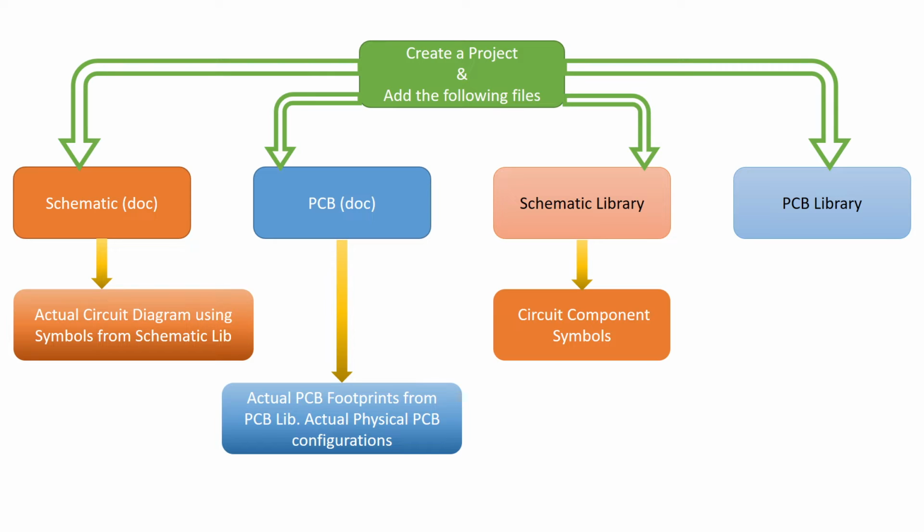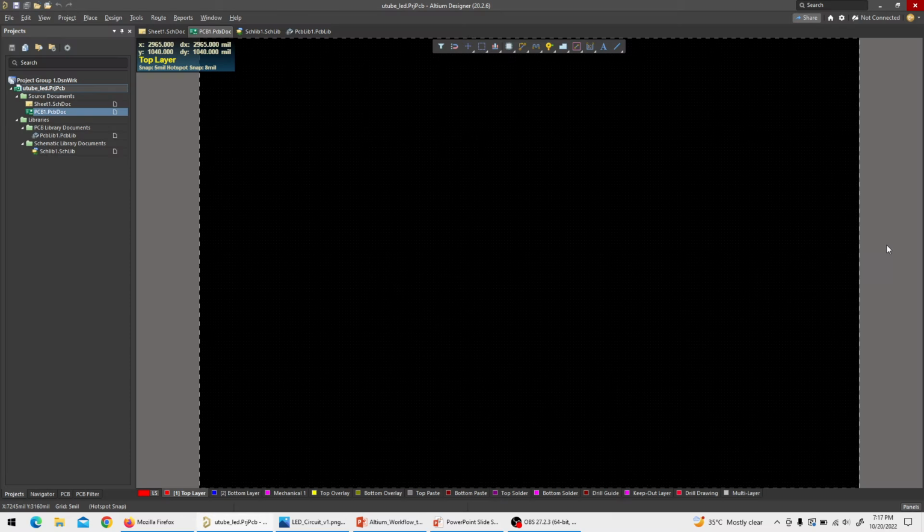In our case, I'm going to use 0805, which is 80 mils by 50 mils, length and width. We're going to create the PCB footprints, meaning the actual PCB pads that will be created by the manufacturer. To get those real pad components, we'll need those footprints, which are available in a PCB library. So we'll have to create a PCB library too. That's the whole thing.